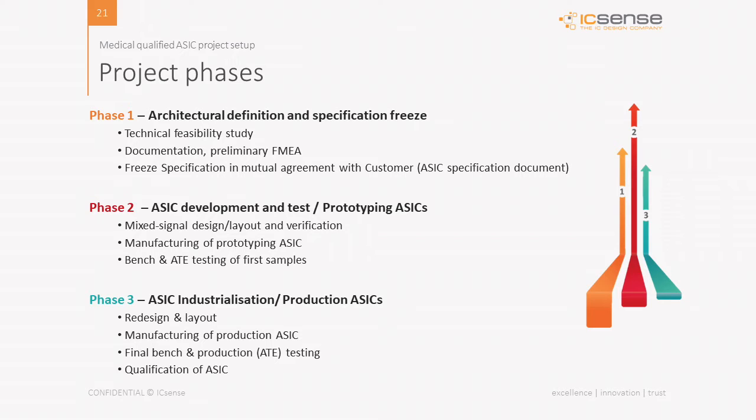Also, this includes specific blocks and aspects needed for testing and manufacturing purposes. And we add some additional circuits to improve our testing capabilities during the design. Within our design, we also take care that our design is robust over a larger range of process, voltage and temperature variations. Chips are not designed to work at one temperature on one voltage and so on. So specs are always mentioned in terms of min-max ranges. So we must make sure that our chip works under all circumstances.